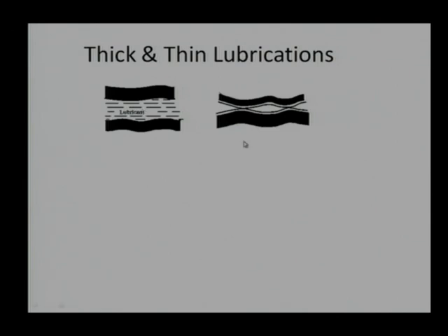However, optimization says that lesser space is always preferable. We need to go ahead with micron size components or nano size components. So, in that case we require this kind of mechanism. That is why, when we design a hard disk drive where space is a major consideration, in that situation we need to reduce this lubricant thickness, maybe on the order of 10 nanometer or 3 to 10 nanometer, much lesser than 10 nanometer.